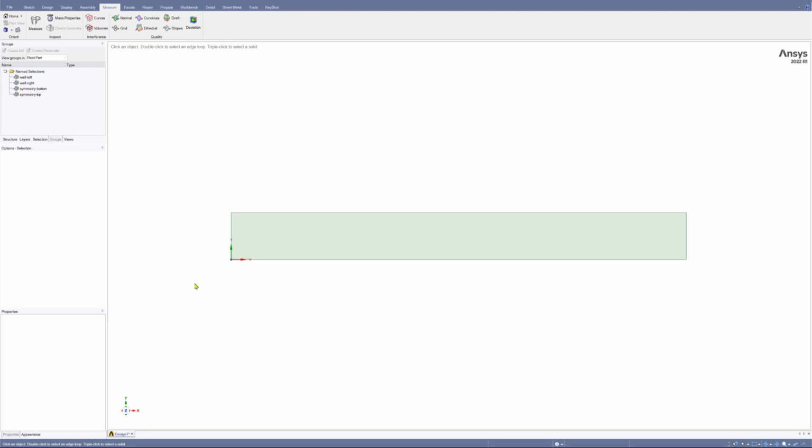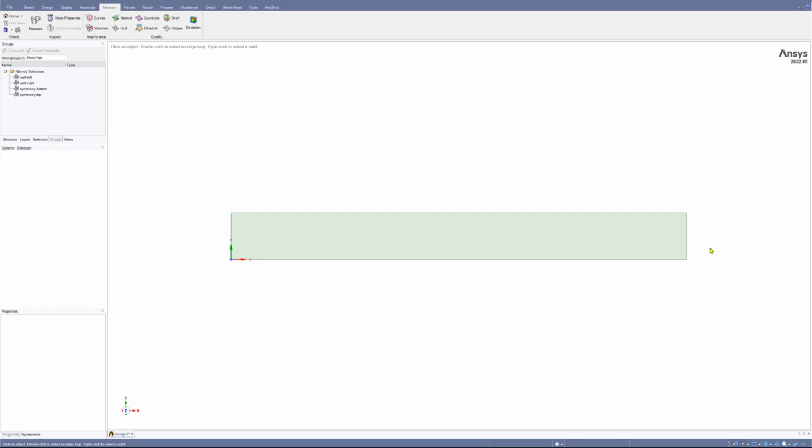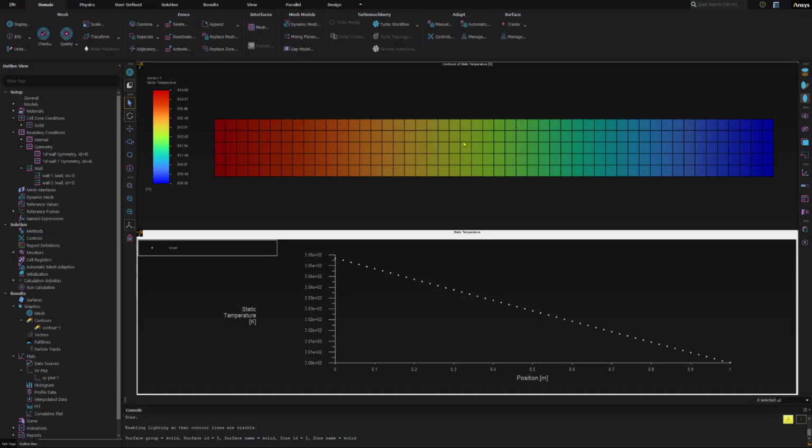So now it's time to go to Ansys Meshing. But the thing is, when you are working in the Workbench like this one, you will see now this task has been completed and it is green. When you have done your work in SpaceClaim, you don't need to save the file. You can just simply close this SpaceClaim. So I will close this SpaceClaim. I don't need this one.